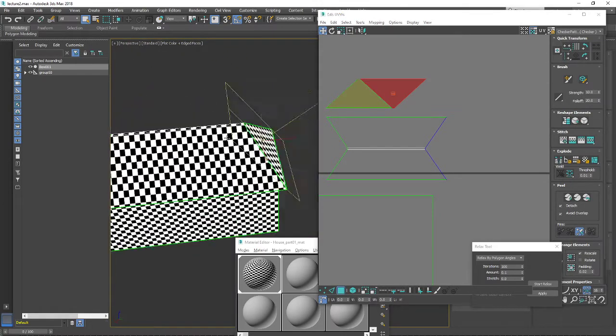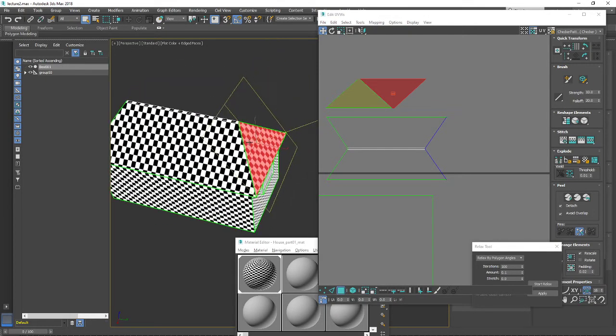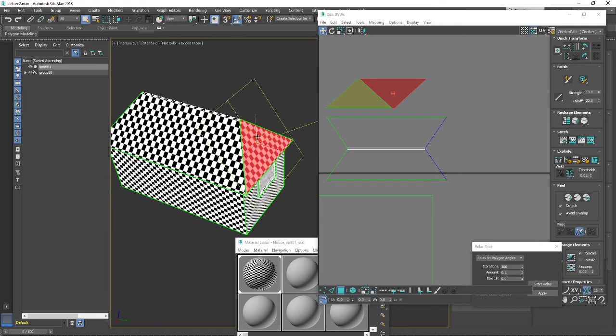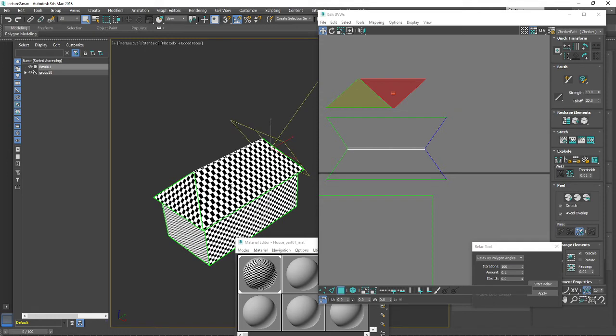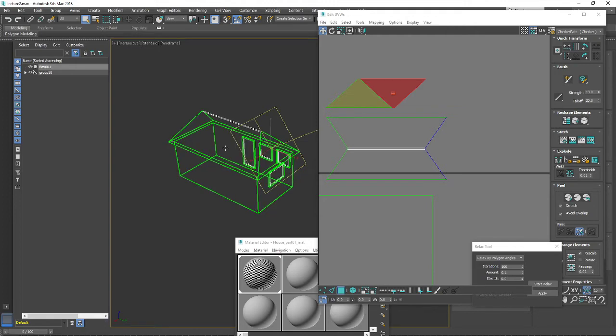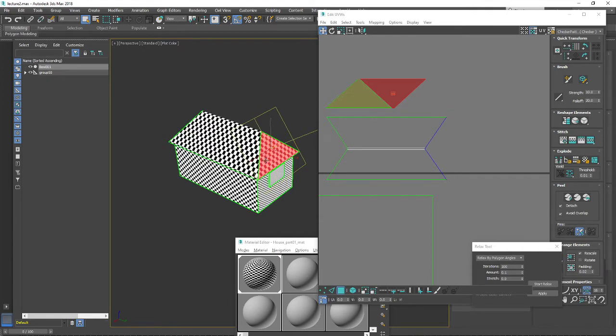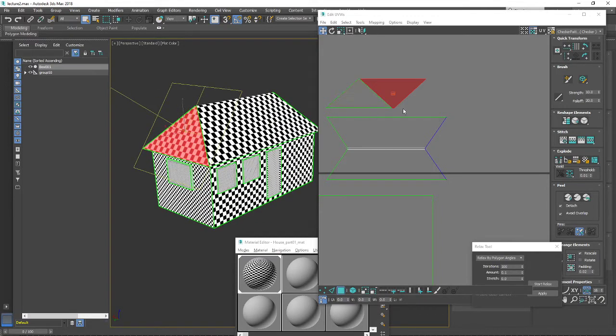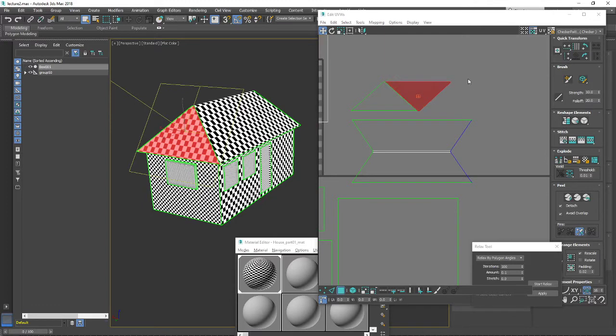If you select that triangle here, also to turn the selection on and off, you can use the F2 button. So if you have some struggle with your selections or shape methods in the viewport, you can always try the F4, F3 and F2 buttons to see how the different selection methods work for you. So by now we have selected this triangle here, and we can see that it should be connected with that part of our unwrap. It should be highlighted with the blue color like this.